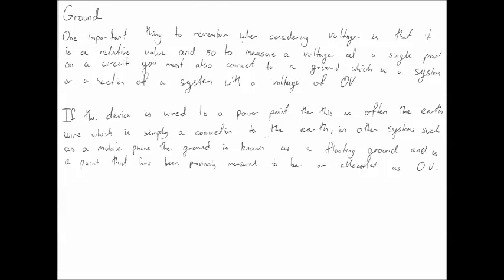Finally, I would like to discuss what is a ground. One important thing to remember when considering voltage is that it has a relative value. And so to measure the voltage at a single point on a circuit, you must also connect to a ground, which is a system, or a section of a system, with a voltage of 0.